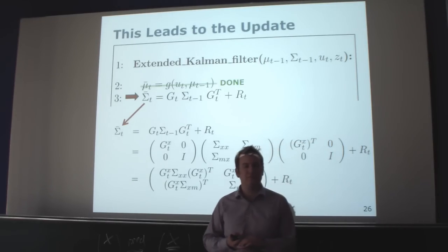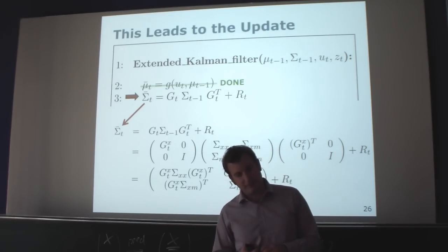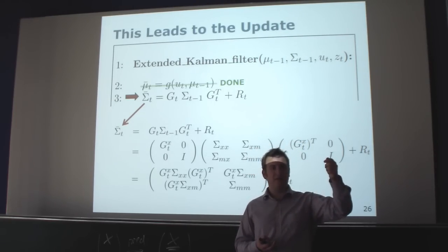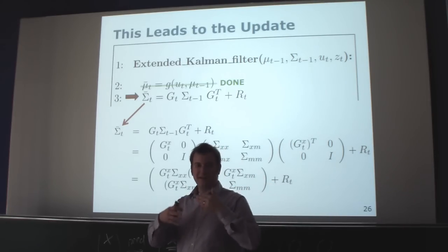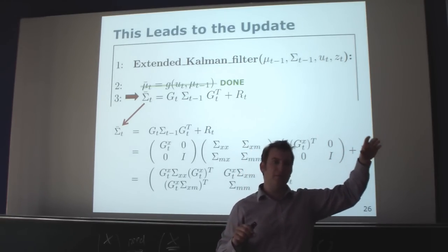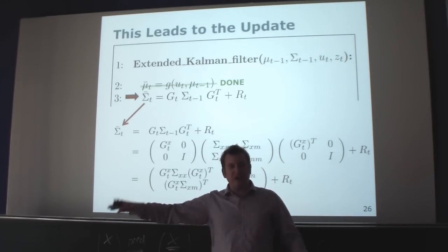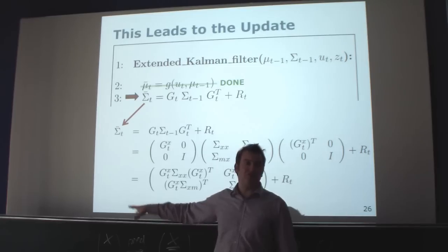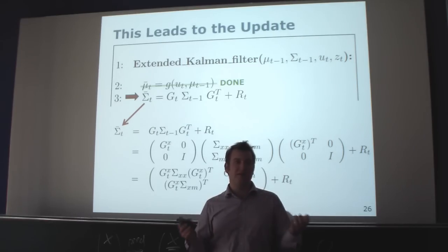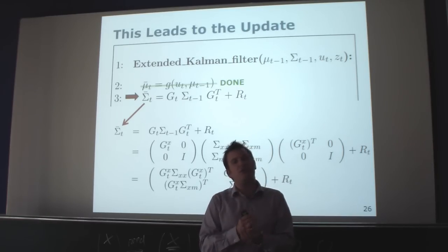And we are only uncertain between two different poses here, I mean, at the prediction. We are in x1 or x1 plus something. Yes. All the Bayes filters do that in this incremental way. So you have one motion which gives you some small increase in uncertainty. If you accumulate that over time, it really gives a real banana shape. If you take a robot and you execute these motion commands 100 times, you will end up with something very similar to a banana-shaped distribution. But this is nothing the Gaussian distribution can represent in here, at least the Gaussian in the xy or xy theta space we have here. So it's clearly the case it's an imperfect model.